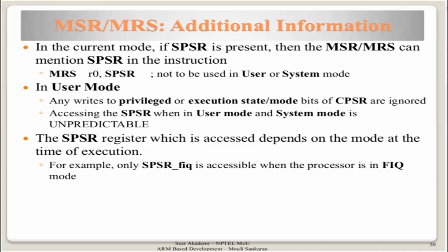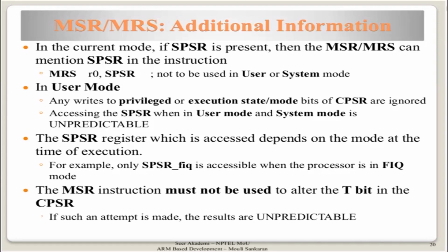Suppose you are in a fast interrupt and you access SPSR, it will access the bank of that particular exception. So you don't have to mention underscore FIQ when writing the code. You will write SPSR, but based on the mode in which the code is executed, it will access the relevant bank register which is active at that moment.